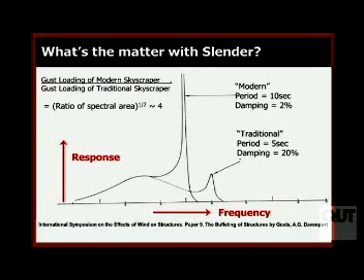Some of you are divers. You will have stood on the end of a diving board and found its natural frequency. You jump up and down on that frequency, you'll get a much bigger response. And so that's what this is telling us. If I have a natural frequency here of, whatever that is, well, it's a 5-second period, so it'd be 1 over that, 0.2 hertz, I might have some response.